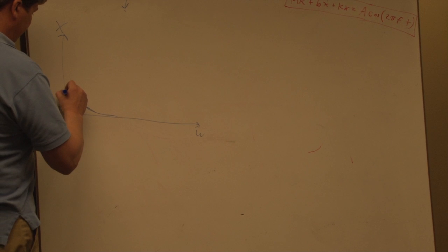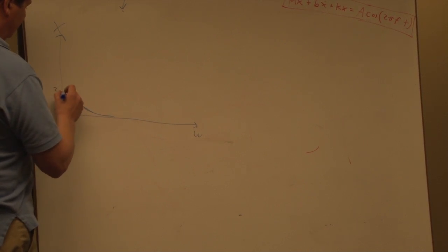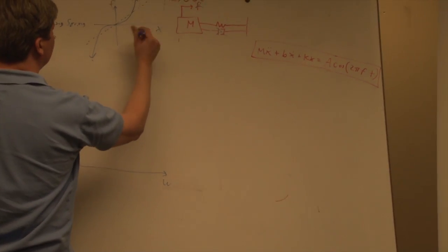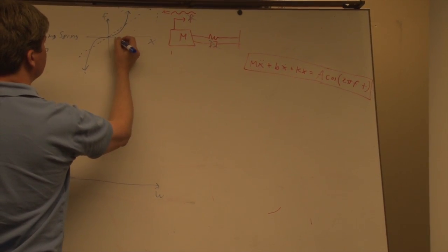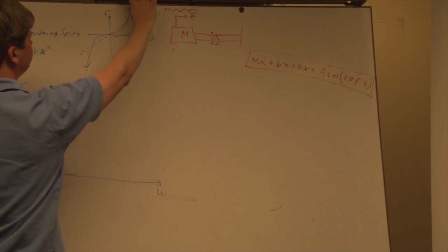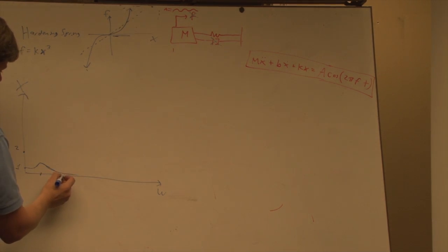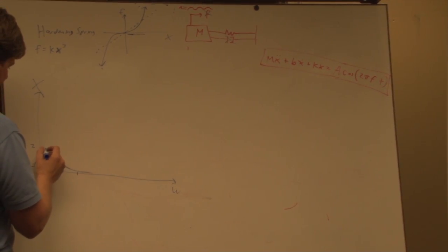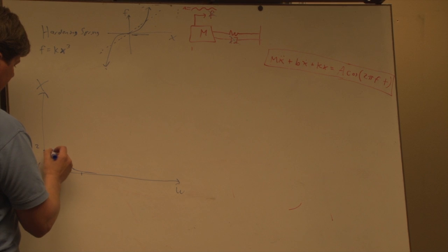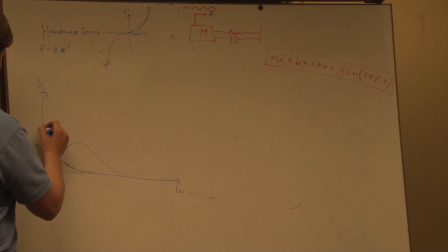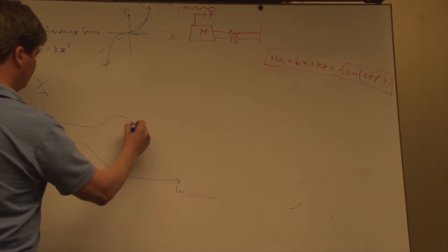So now if you drive at higher amplitude too, then your resonance is going to be higher, because at that amplitude, your output is going to reach out further, so now you're stiffer. If it was a linear system, you'd just have a larger resonance, but with the nonlinear system, you still have a resonant looking curve. So it might look like that. And then at 4, something higher, it might be even further out.